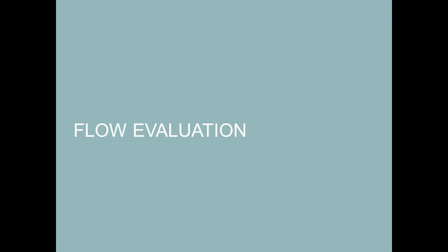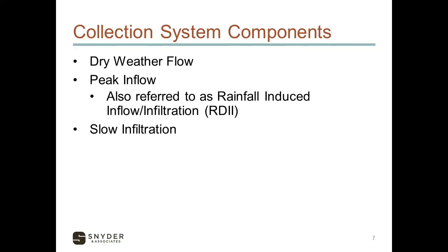Jumping into flow evaluation, just want to do a quick summary of what are the 3 components that we will break out when we're actually going through a flow assessment. Dry weather flow, peak inflow, also referred to as rainfall-induced inflow and infiltration, RDII, and then slow infiltration. We're going to go into each of those in a little more detail in a few slides.